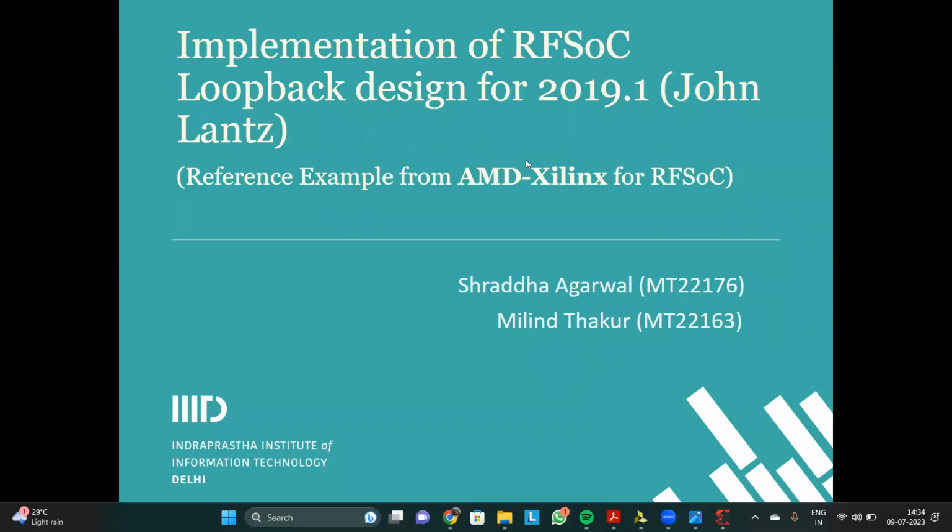Hello, this is a continuation video for the implementation of the RFSoC loopback design, which is a reference example from AMD Xilinx. In part 1 of the video, we have already generated the clock files that will be used to configure the RFSoC board. Since in the block design we do not have the RFSoC board separately, we will be using a ZCU111 interface software to configure the board.